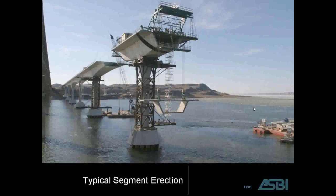The segments then are held apart slightly. Epoxy is applied to the joint, and then post-tensioning is applied to pull the segments up into the final position.